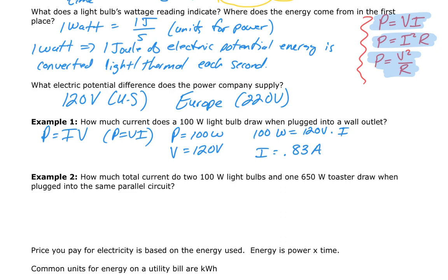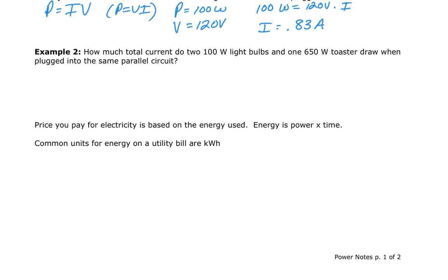Let's take a look now at what happens if we set up 2 light bulbs. We're going to use a parallel circuit. Why do we use a parallel circuit? Well, think back. If I have one light bulb here and I want it to stay on and I don't want the brightness to dim, I need to make sure that the second light bulb is connected in parallel, or the first light bulb will dim, and that doesn't do me any good. I don't want that happening. So the circuits in your house are all wired in parallel so that you don't have to run your refrigerator just for your microwave to work, or vice versa, and so that your lights will have the same brightness regardless of how many are turned on.